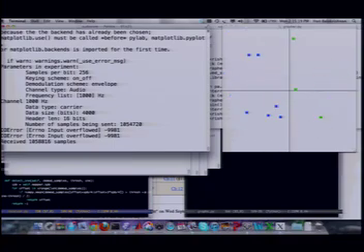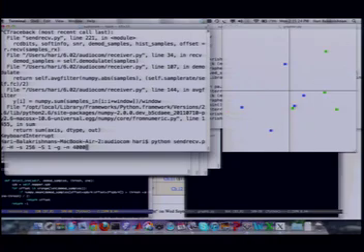I'm going to do this again so you can see what's going on. As the amount of noise increases, you can imagine what's going on here in the signaling. This is called bipolar signaling, where you might send a bit 0 as a particular kind of sinusoid and a bit 1 the other way, as the other kind. So the idea would be that the zeros get mapped to the left, the ones get mapped to the right, and as we increase the amount of noise, you can start to see that they cross over, and we'll be making errors in our estimation.